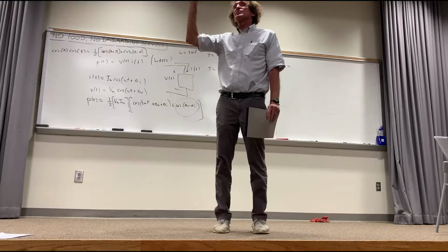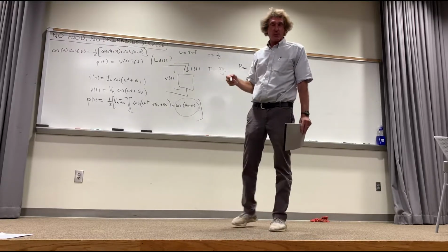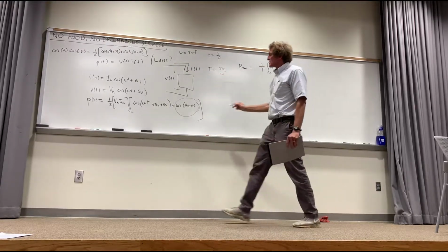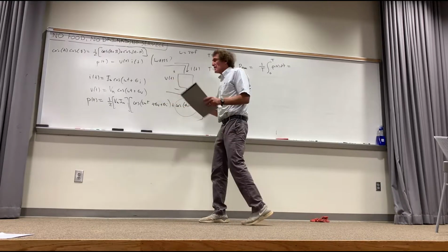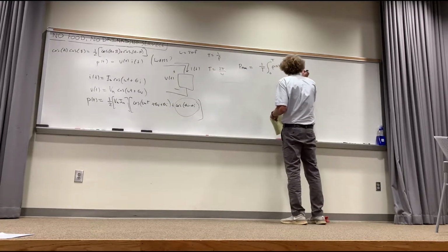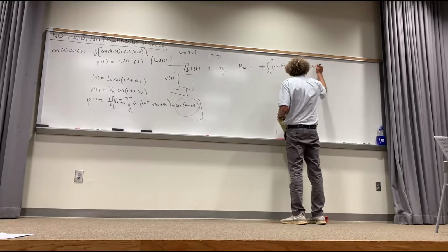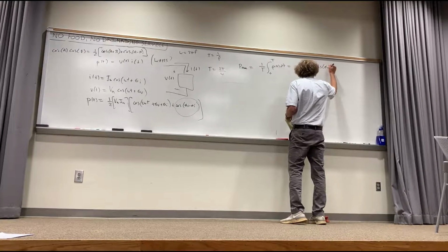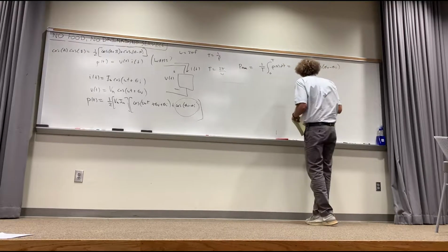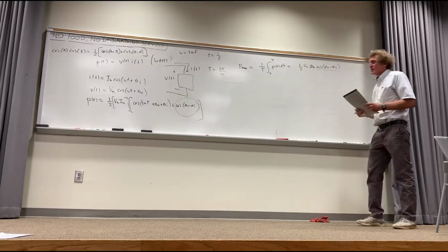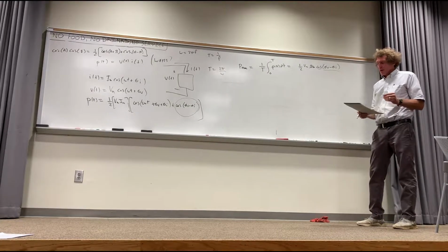If you integrate it over 2 cycles, it's still the same, 2 periods. So that means this time variation will be taken out of it. And the average power here simply becomes, and write that down, 1/2 Vm times Im times the cosine of theta v minus theta i. We're going to come back to this term in a bit. That's actually called the power factor.